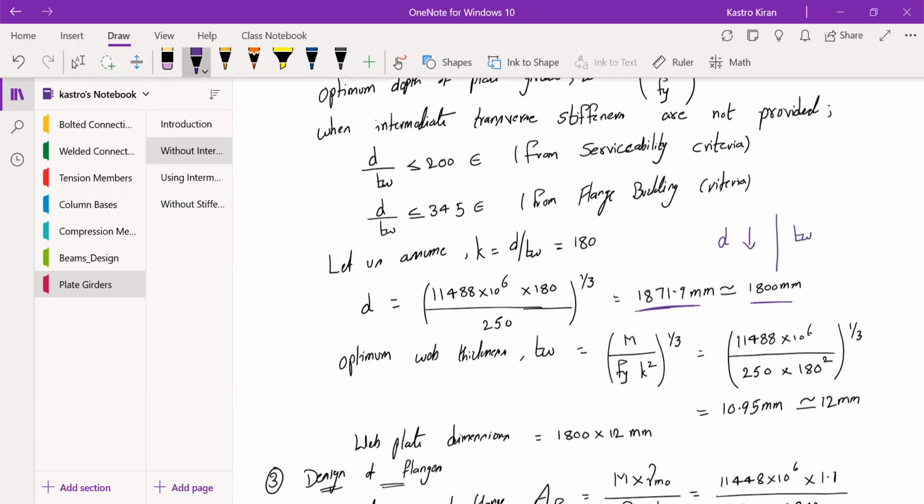So you have got 10.95 mm as the thickness of the web, and what we have done is we have increased the thickness of the web. Remember this. This is the concept which is involved here. So in the model 1 problem, whatever depth we have got, we have decreased the depth and then assumed some depth value. But the thickness of the web, whatever we have got, that is 10.95 mm, we have increased the thickness of the web and then designed the problem.